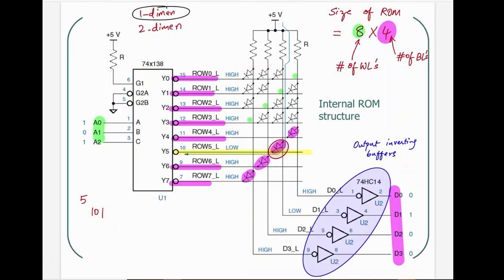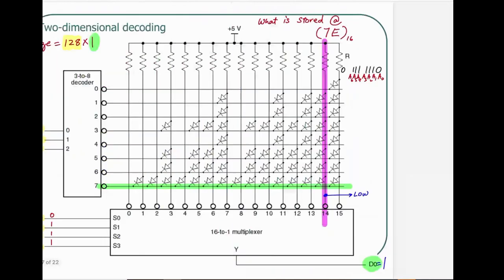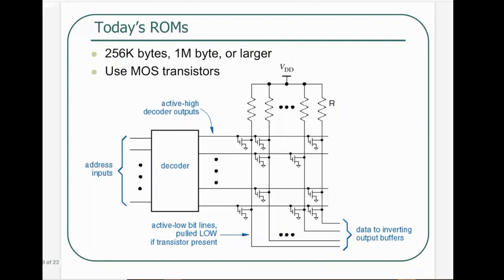So we would want that similar thing to transition to a MOS transistor based architecture, where the presence of the transistor should be equivalent to making it into a 1, and absence of the transistor should be equivalent to storing a 0 there at that particular location.